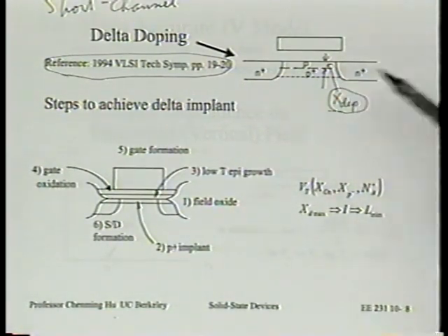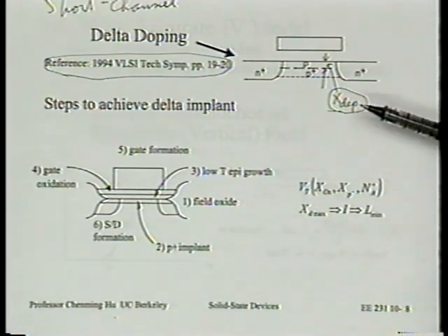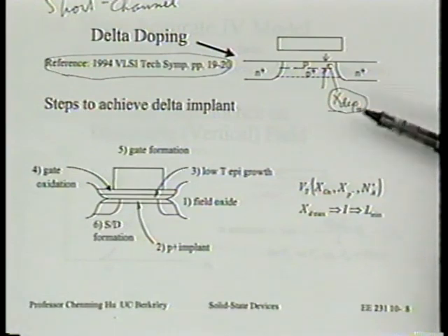So that is the attractiveness of retrograde doping. It really is that. Not many people realize that's what it is, and certainly people don't put it in those terms, but that's really what it is. It allows you to reduce the depletion thickness by half while maintaining a desired VT.